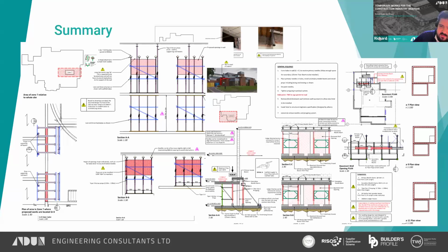And you have to remember to take into account the grand scheme that even though you're making openings on the first floor, it doesn't mean you don't need to back prop on the ground floor to make sure the load paths are correct and the floors can take all the loadings. And I think at that, I'll pass it back to you, Josh.